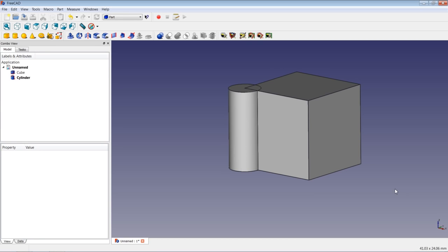When talking about 3D objects, we have to distinguish between mesh objects and solids. Mesh objects consist only of faces, while solids have an inner volume. Typical file formats for mesh objects are OBJ and STL. A very well-known file format for solids is the STEP format.